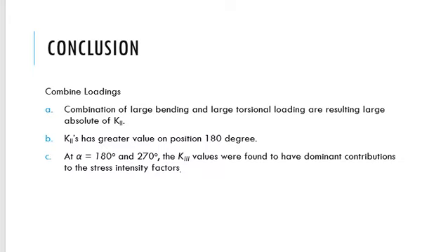For the combined loading, the combination of large bending and large torsion resulted in a large absolute K2. K2 has greater value at positions under 80 degrees. At 180 and 270 degrees, the K3 value was found to have a dominant contribution to the stress intensity factor.